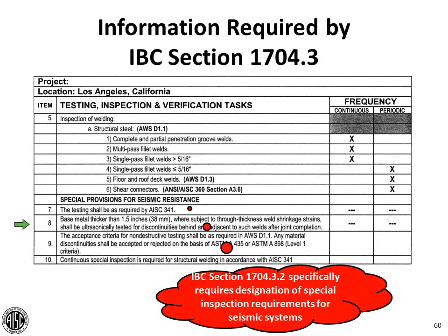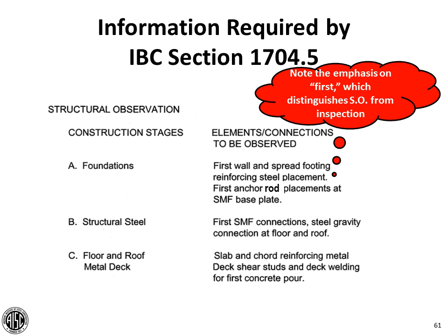In particular, the building code requires that if a project has seismic detailing requirements, that those inspection requirements be specifically listed. And so here is a listing of some of them. The majority of the seismic inspection requirements have been referred to through reference to AISC 341 rather than repeating the same things that are already, I think, fairly clearly presented in Chapter J.